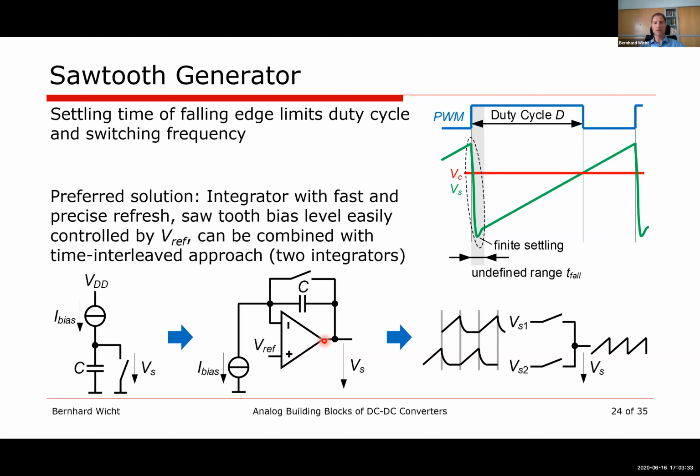So that's an easy circuit to be implemented. If you have a fast switching, we may even implement 2 of these circuits and operate them in a time interleaved manner so that we get a nice triangular sawtooth ramp as shown here. So we have verified that up to 50 megahertz, it really works nicely if we do that this way.